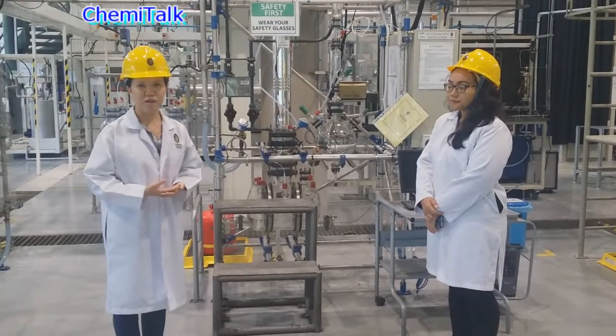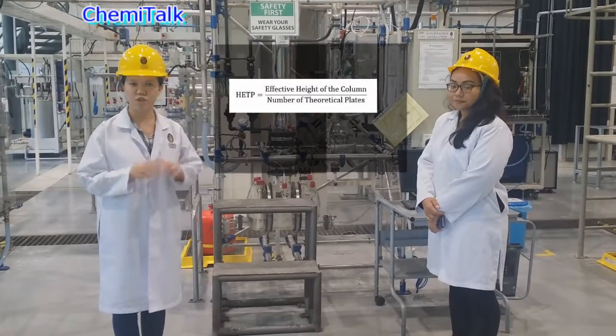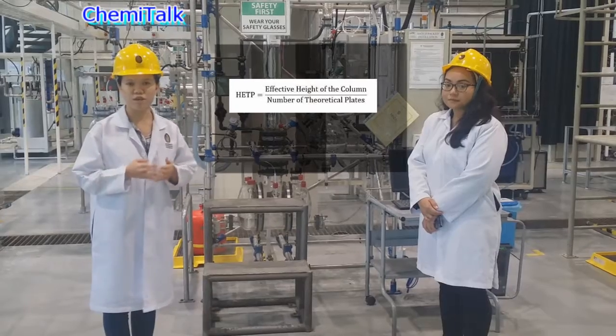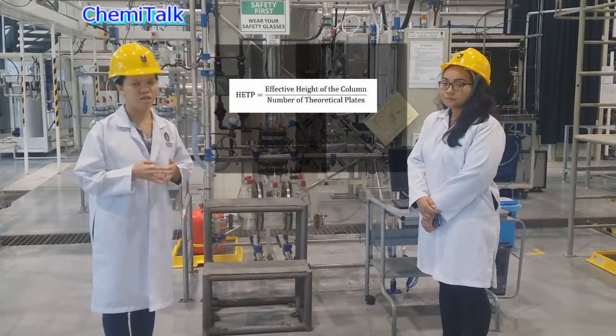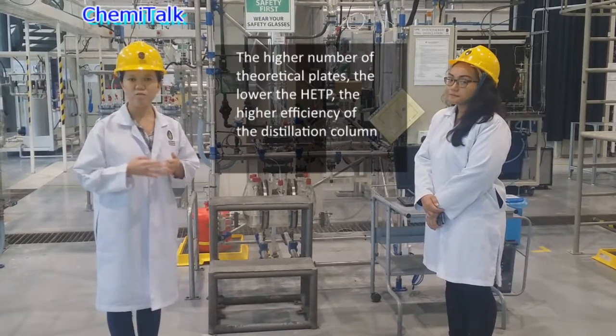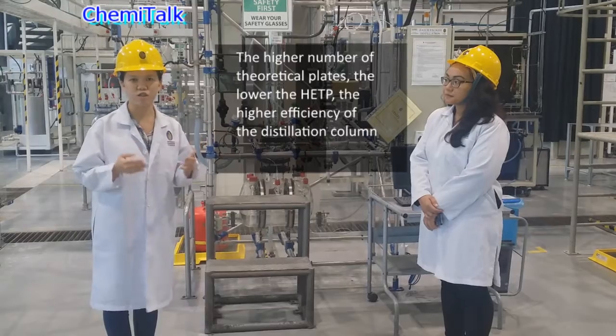HETP is defined as the effective height of the column divided by the number of theoretical stages. Theoretically, the higher the number of theoretical plates, the higher the efficiency of the batch pack distillation column. This means that a lower HETP will result in a higher efficiency column.